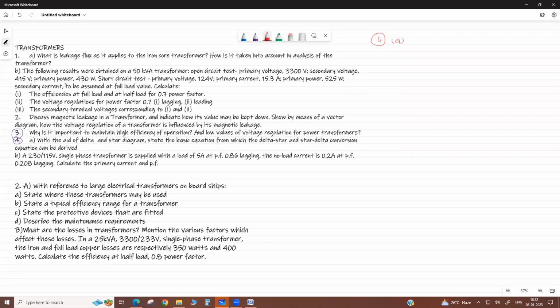Okay, you just check what is the kilowatt. If we know the motor rating, kilowatt rating or HP rating, then we can calculate what is the starting current based on the motor full load current and the starting current. We have to select the switching means, starter components, meaning the rating of your fuse or MCCB, then your overload relay.